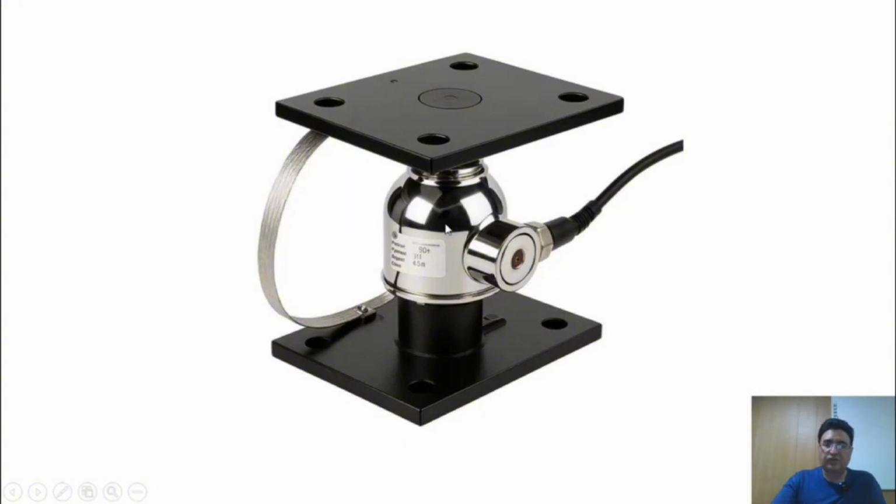As we mentioned, these load cells come with their own mounting. That means there is a plate below the load cell and a plate above the load cell, so we can apply force to the top plate. And since these load cells are often installed outdoors, what you see here is specifically called a lightning arrestor. If lightning ever strikes the very top part of this mounting, it will be safely conducted by this specialized wire you see here to the bottom plate. And since the bottom plate is securely grounded, it can effectively and safely discharge the lightning for us.